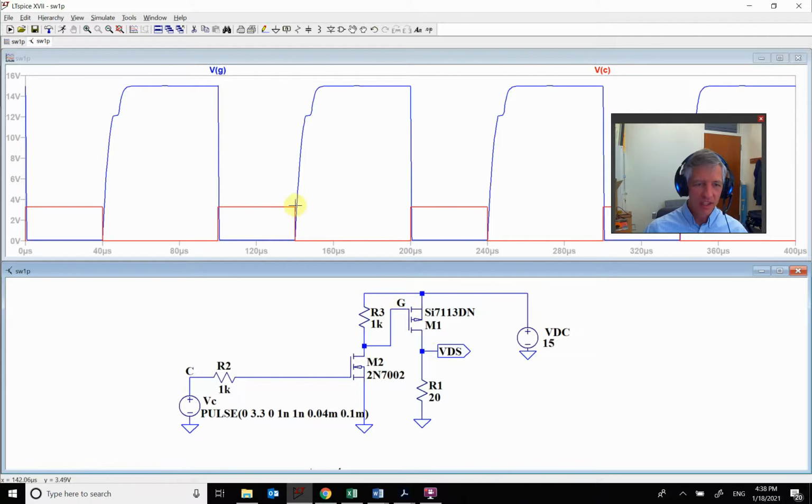Now, when this one goes down, this becomes an open circuit. That would be like removing this. So when this one goes into cutoff, this becomes an open circuit. Well, now what is my gate tied to? My gate is tied through this resistor up here. So this is my resistor. Rather than almost zero, a really small resistance, we have a really large resistance.